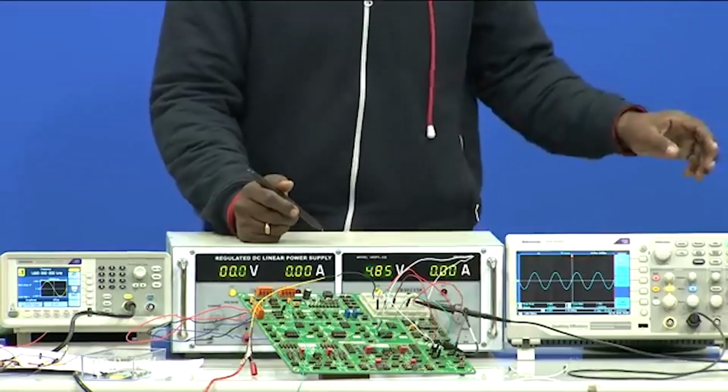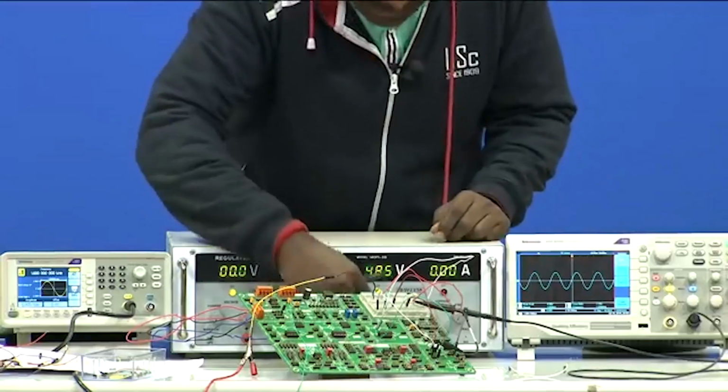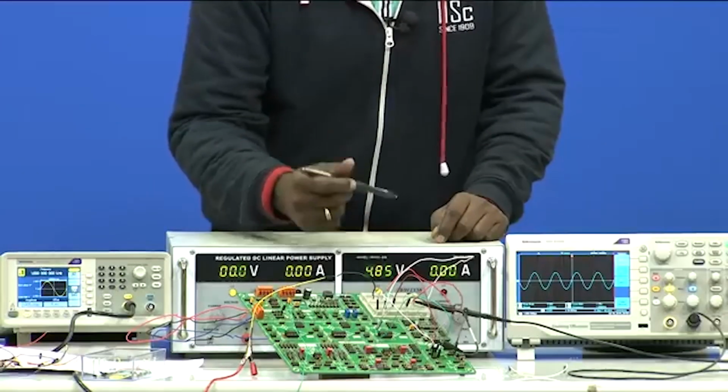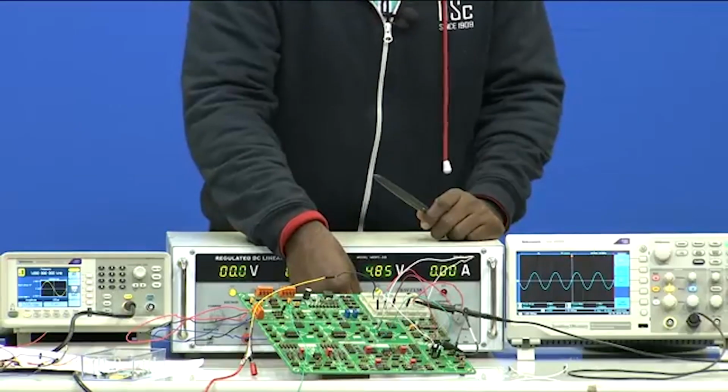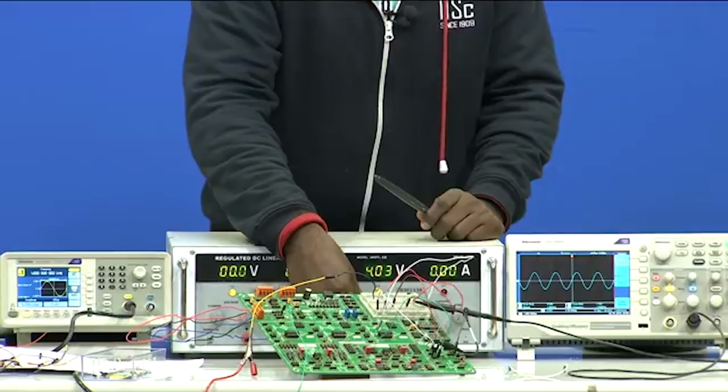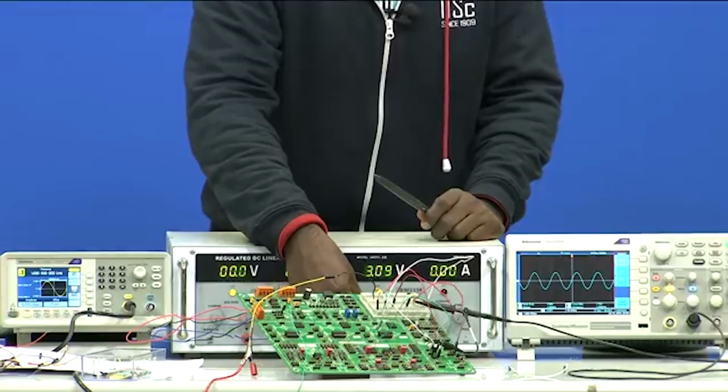So, that means it is not clamping because the reference value is higher. So, I will slowly decrease. It shows a positive, which is nothing but the negative that we are applying. So, I am slowly decreasing. Till 2.5 we will not see any shift of your output signal. When we come close to 2.5, I will use a fine knob. Right, so this is 2.5. I have applied 2.5.